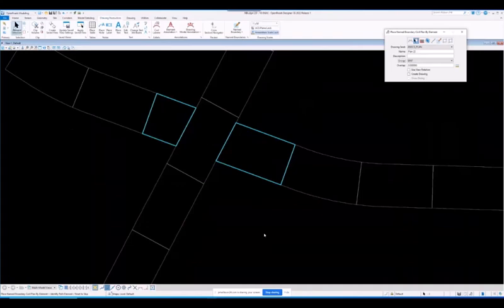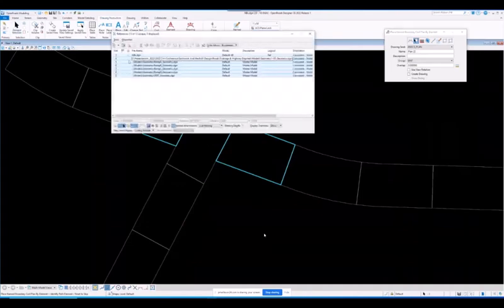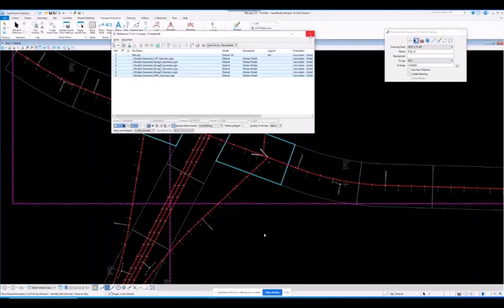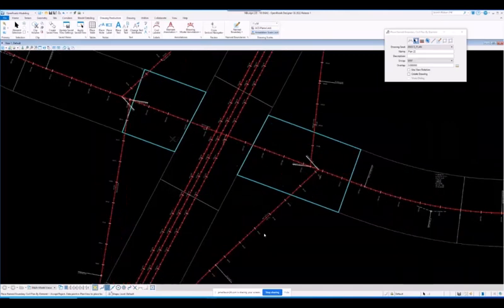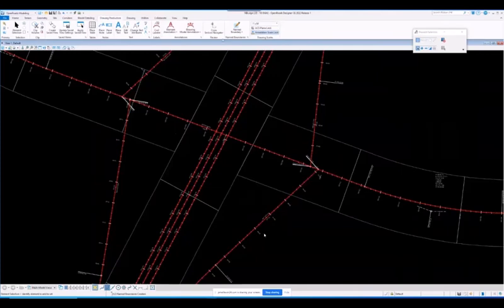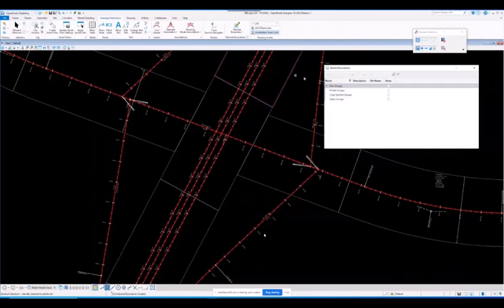And I need to turn on the existing geometry here. I almost forgot, because I want some EC attributes for the stationing there. It helps us with reporting. You get additional information. Pick that, and it asks you, do you want to take the selection set? I'm going to accept that, and I added those 2 name boundaries to the group that I just created after I deleted the first 2 for the SR97. So pretty quick. It's customizable. MicroStation shapes, name boundary tools, it doesn't matter.